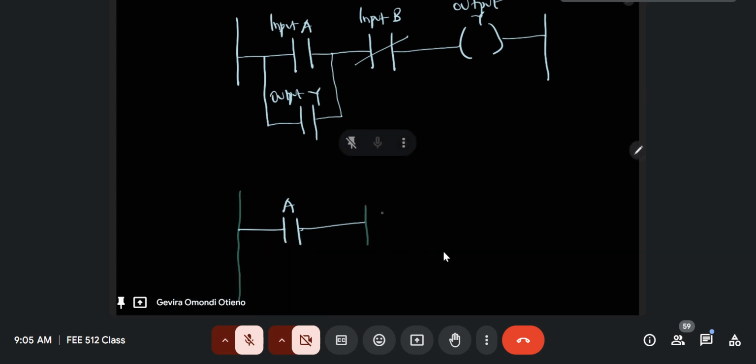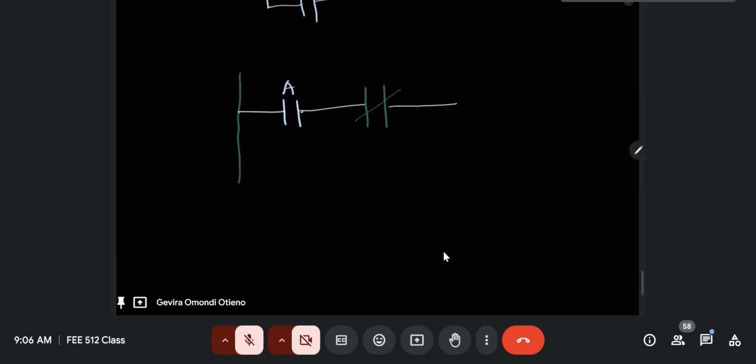So allow me to draw it like that, because it's already allowing logic to pass through. Please note, again, let me just take a breather here. Remember, we had said we have two conditions for the normally open contact. So for the normally open contact, let me say this is false and this is true. This is logic 0, this is logic 1, or high, or whatever. If this is false, then we have it like that, meaning it will show as inactive.